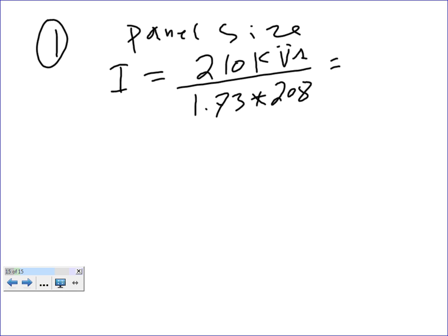Camille, what does your Excel sheet say? 583. 503? 583. 583. Thank you. I might have to check my vision, my hearing, guys. Now, disclaimer. The 310 that I gave you guys has already been derated. Okay? This is the derated. Remember that first 10 at 100%, higher than 10, cut it by 50. It's already been derated. So don't multiply by anything else. That's already derated, sized.